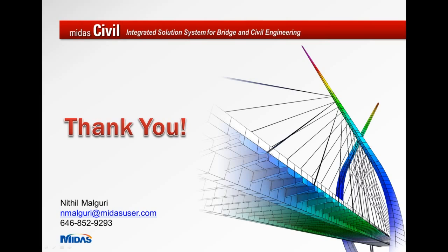There is another question by Mohammed. The question is, should we consider two opposite direction springs at each pile section to consider passive active situation? Well, in the case of pile, there is no passive or active situation, because if it goes towards one end, it's passive for one side and active for another side. So we just model one spring that contains the stiffness for active in both regions, because active is higher than the passive one.